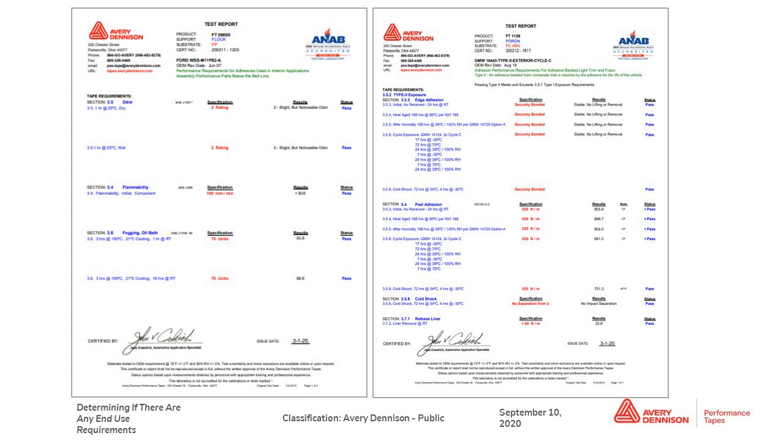And then if you look down the lower section here, this is peel adhesion. These are the same conditions, except now we're going to peel the product after exposing it to that condition. And here the specification is requiring a peel adhesion of 525 newtons per meter. And a lot of times you'll have a lot of different units. What's most common in the United States is pounds per inch. We would convert those units in our heads to understand what's easier for us if we're usually coming from a pounds per inch perspective. But that's the specification.